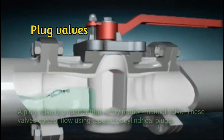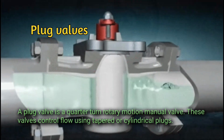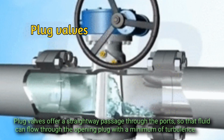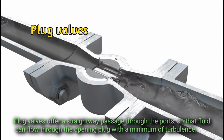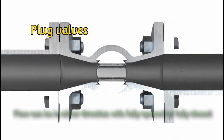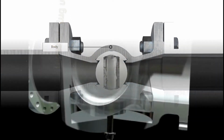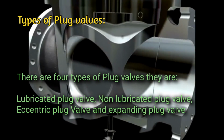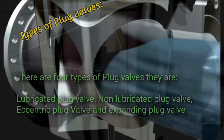Plug valves. A plug valve is a quarter-turn rotary motion manual valve. These valves control flow using tapered or cylindrical plugs. Plug valves offer a straightway passage through the ports, so that fluid can flow through the opening plug with a minimum of turbulence. Flow can be in either direction with fully opened or fully closed. Types of plug valves. There are 4 types of plug valves. They are lubricated plug valves, non-lubricated plug valves, eccentric plug valve, and expanding plug valve.